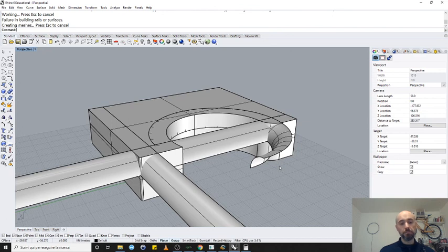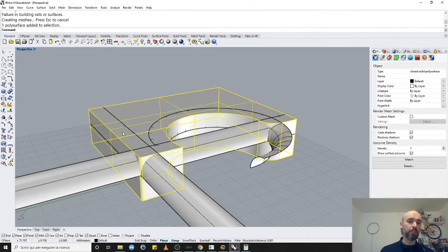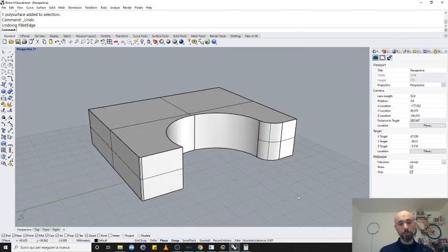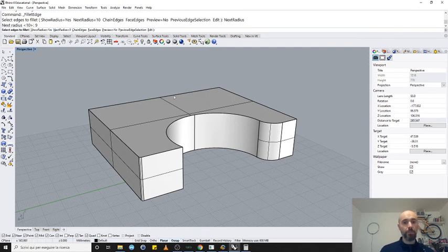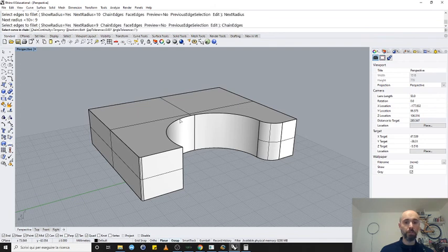but still, if you are patient, you can explode the solid, cut the solid with the surfaces that it creates, and you get the fillet anyway. Now this was done on purpose by me to show you a potential problem. If you have a fillet and the radius is less than the one you want to fillet, then it should work better.